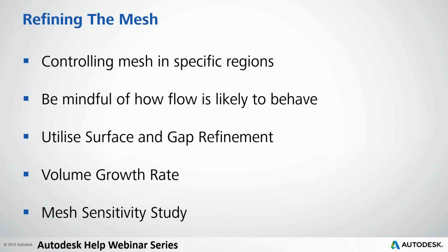Utilize the surface and gap refinement almost always now. I think you probably agree, Todd. I at least always have surface refinement on, and more often than not gap refinement as well. But you've got to remember that gap refinement will default to 1 gap element in the advanced box that Todd will show you shortly. Ideally, we want to change that to 3 as a minimum.